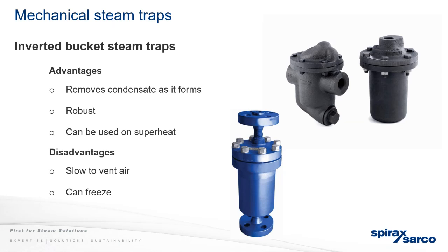So from a cost point of view, it's much more effective for you to repair the traps you have than to buy new ones. Of course, everything has a shelf life. At some point, you will have to replace the whole trap, but they can go on for many, many years before you need to. Cornelius, when you're on site, I imagine you see the same schedule, so we would recommend at least these are inspected once a year, probably change of parts internally every 2 years.